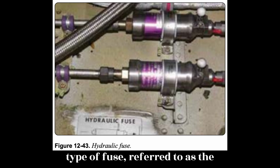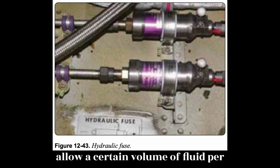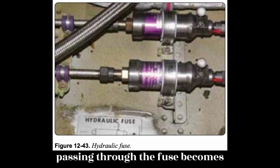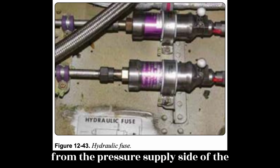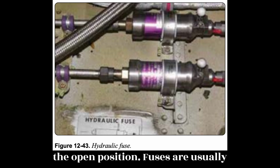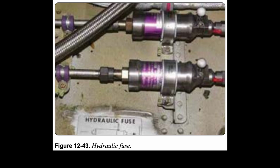One type of fuse, referred to as the automatic resetting type, is designed to allow a certain volume of fluid per minute to pass through it. If the volume passing through the fuse becomes excessive, the fuse closes and shuts off the flow. When the pressure is removed from the pressure supply side of the fuse, it automatically resets itself to the open position. Fuses are usually cylindrical in shape, with an inlet and outlet port at opposite ends.